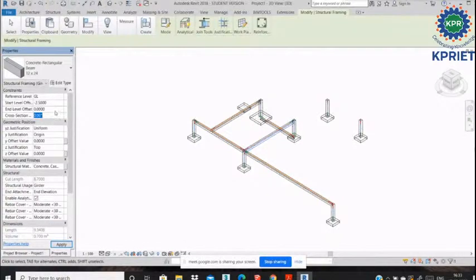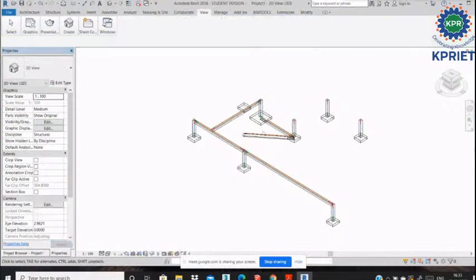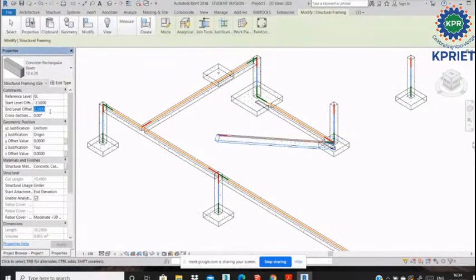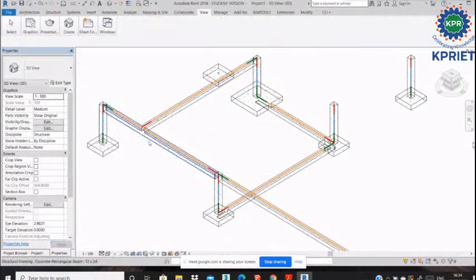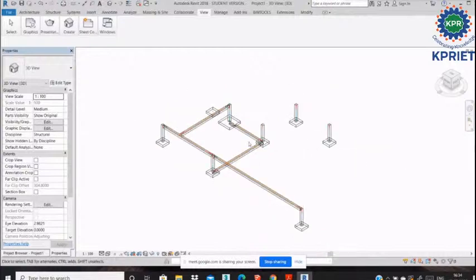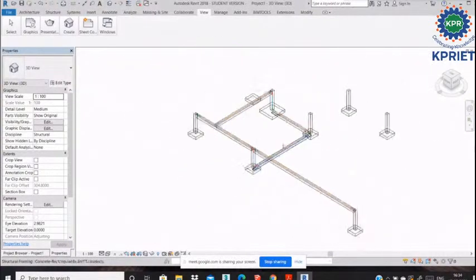Then the other also minus 2.5, enter, right? Now click this minus, right? Minus 2.5, enter, right? Now you see it automatically creates the beams, right? It creates the grade beam from any beam, right? Length beam or grade beam, any beam, you can create these levels, right?